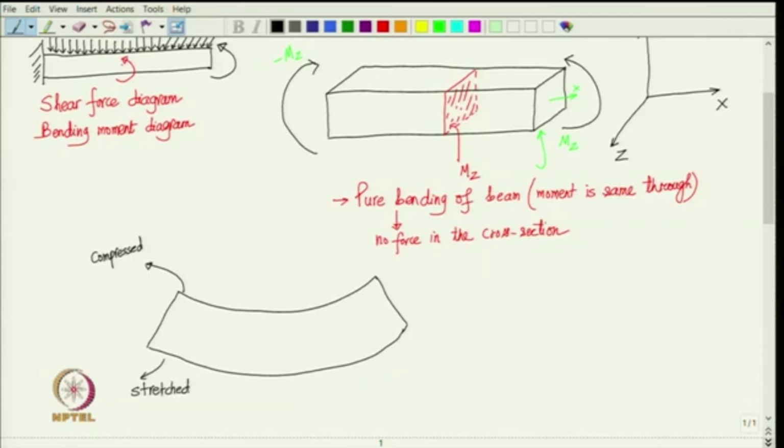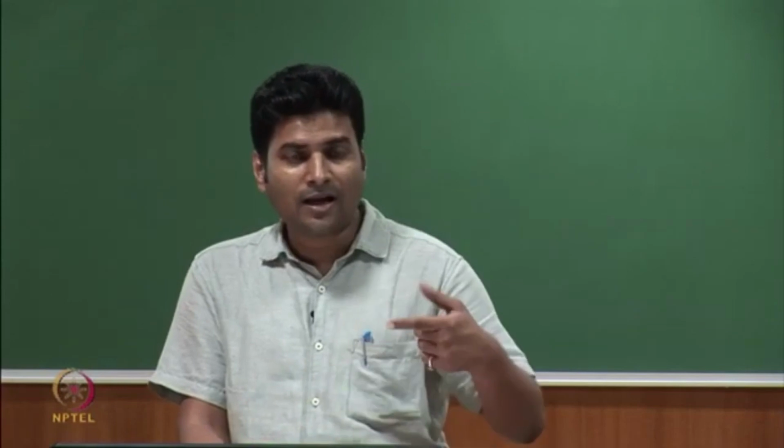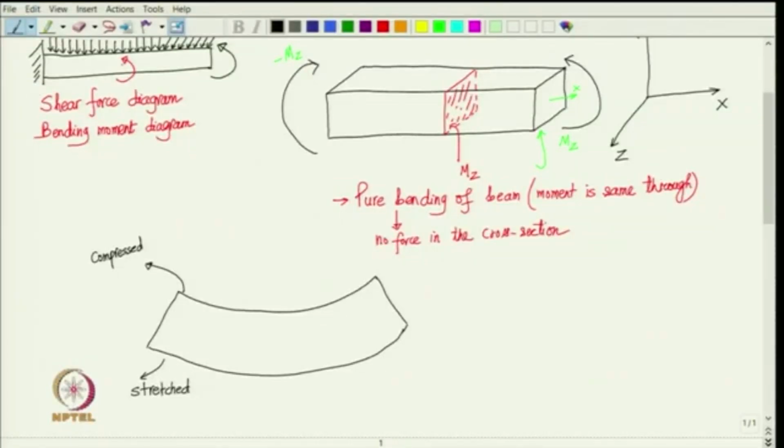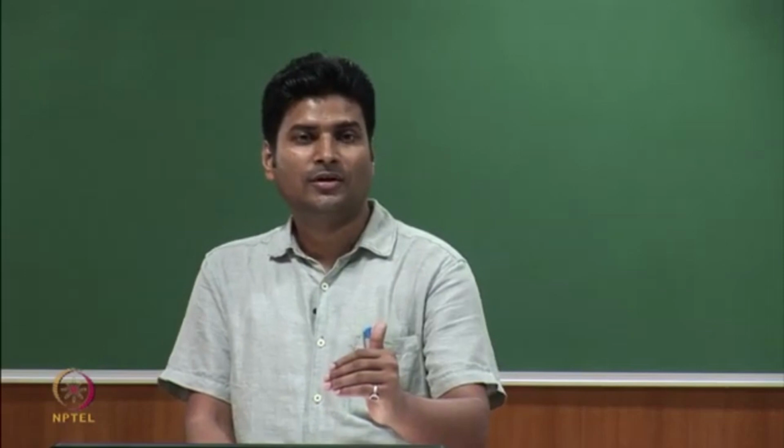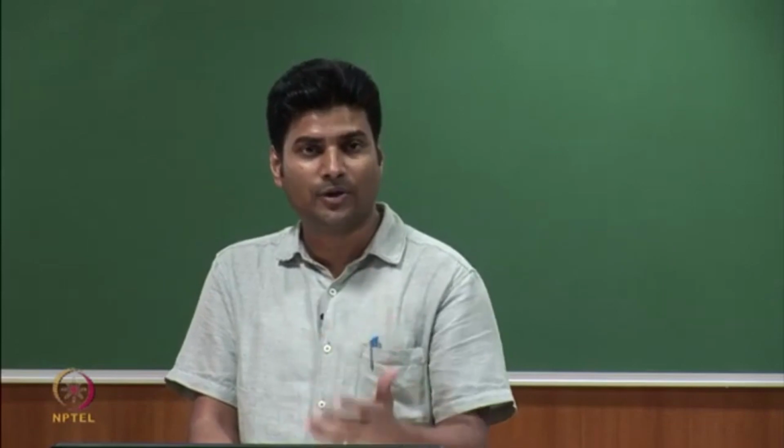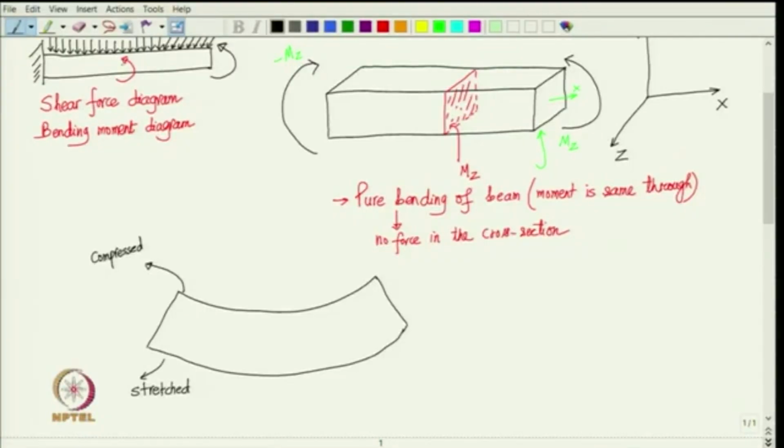So, you can actually think of any line along the axis of the beam on the bottom surface, and due to this deformation that line is getting stretched, right, whereas any line along the axis on the top surface is getting compressed. So, you see as you go from bottom to the top, the deformation is changing from being stretched to being compressed. So, there has to be somewhere a line which will neither get stretched nor compressed, right, because this has to change in a continuous fashion, right.